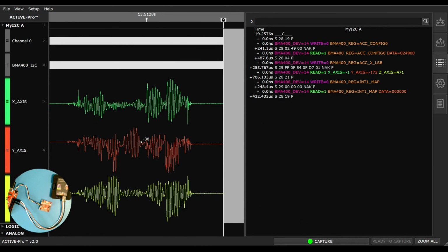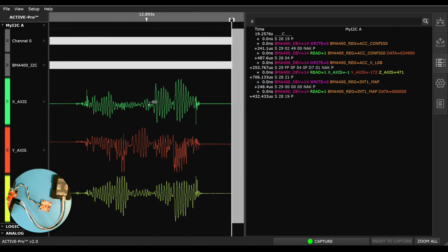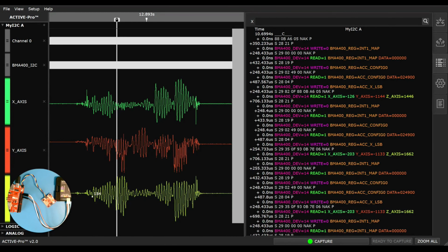And as we zoom out, you see the wiggles. This is exactly what I did. You can then see, wow, how that ESP32 is actually gathering that data off the I2C bus. So this is extremely helpful, to be able to see the I2C traffic, to be able to decode it, to actually be able to graph the fields within the I2C packet.